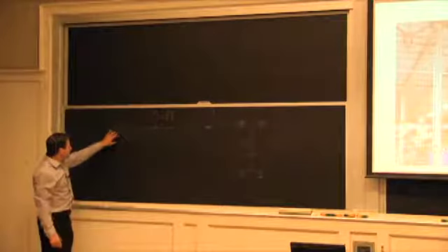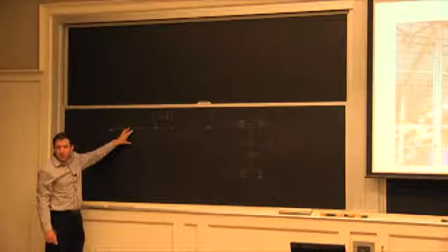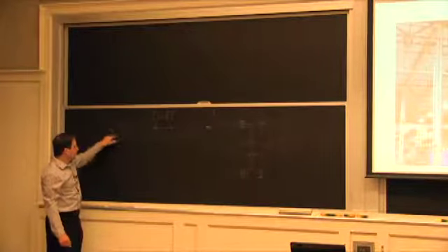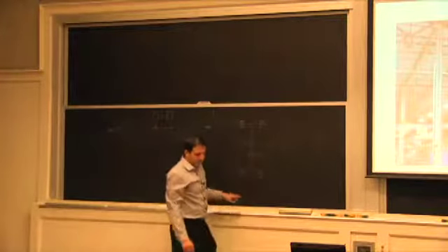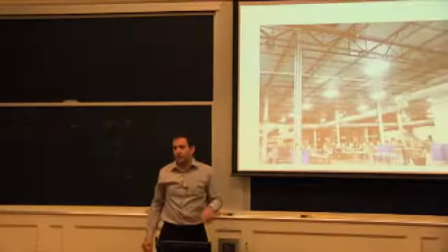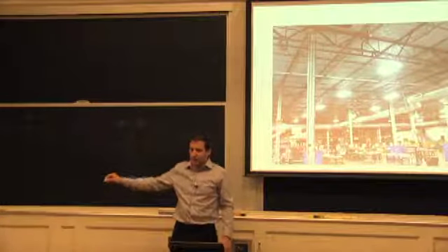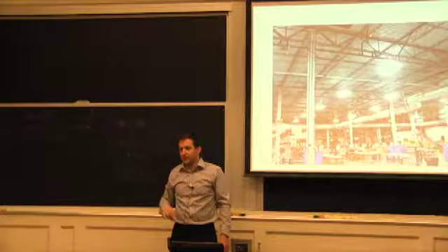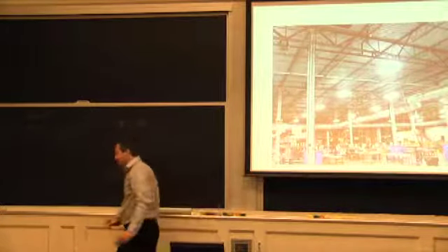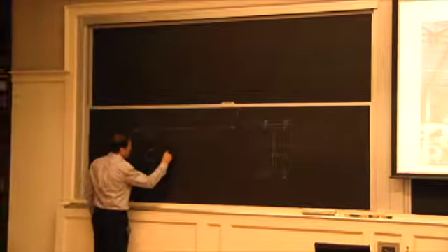As a designer, you can say, well, I'm going to play with the thickness here if I want to. I can play with the size of the members. I can put more diagonals at the beginning. A lot of it, I found out, was based on buckling and deflection. So if I come with the amount of steel that's on the joist and I join it properly, it will buckle before it fails. But from a manufacturing standpoint, when we come to capacities, people come to the assumption that I need a geometry that's right.